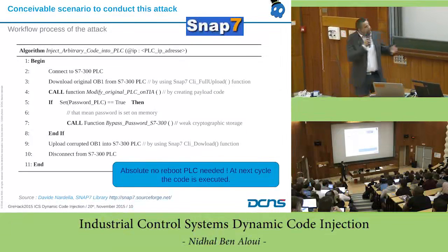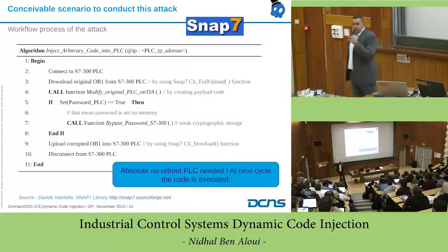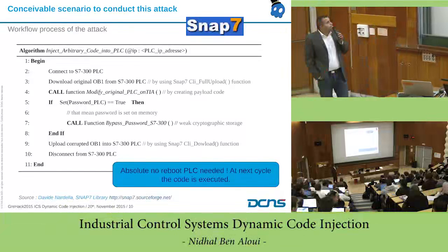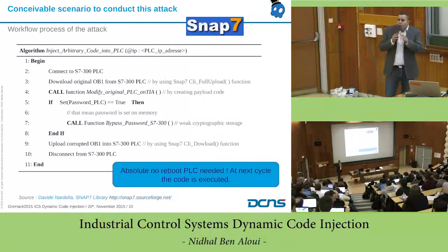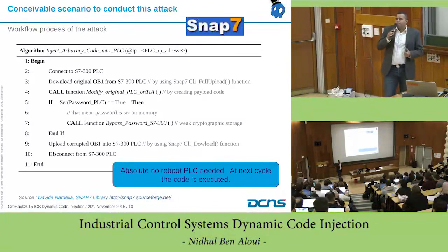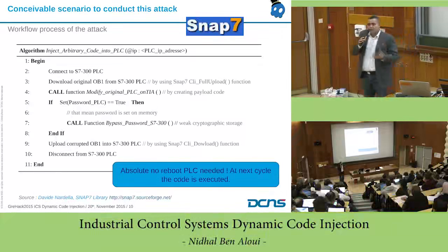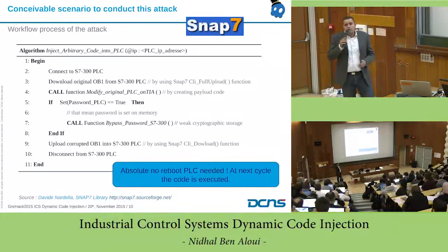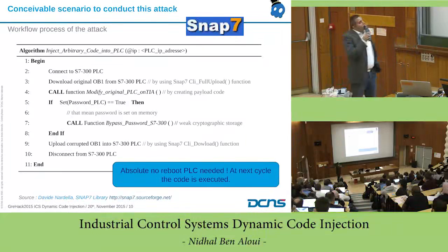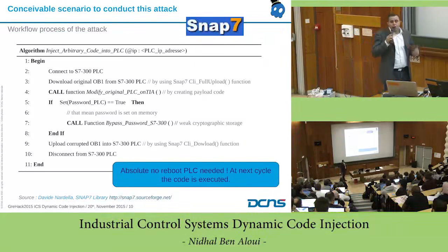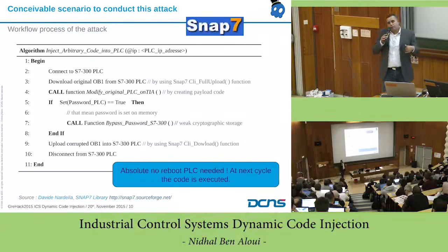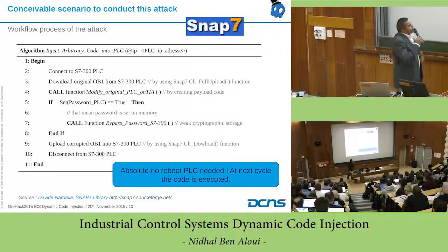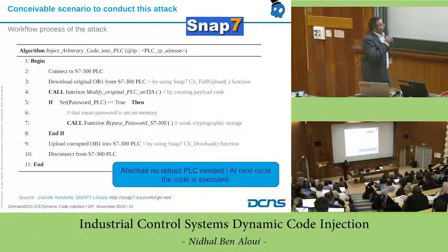So we found on the internet a Python script with which we can bypass the password by brute forcing it, because you can make multiple attempts to put the password, and the number of attempts to try a password is not limited on the PLC. Or you can also read the specific area where the cipher password is stored, then brute force this on your PC. We have done this test in the laboratory.